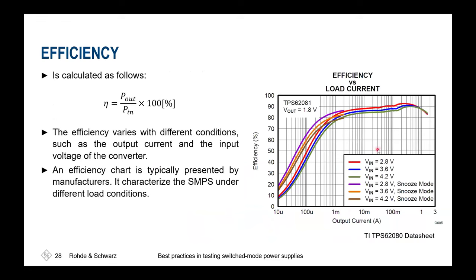In addition, we might not only look at this for one working condition, as this is strongly depending on the load we are using there, and thus you'll typically get many such curves, some in snooze mode, some with defined loads. This gives you an immediate overview of the overall power consumption, which might be crucial if you design a small battery-powered IoT device, which shall only wake up every now and then. And then it's important to know how much current is drawn for which working condition to do a lifetime assumption of that battery.